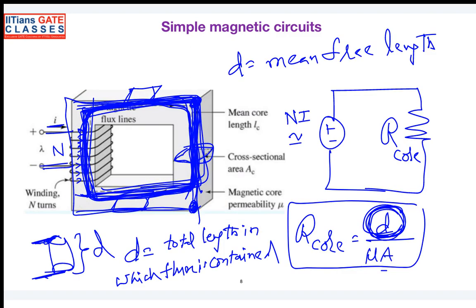What we came across till now is that when current is in this loop, there is a perpendicular flux. But in this particular case, you said it's in the entire core. No, the coil is not around the entire core, right? I was telling about this one. Whatever the dimensions of this core are, it is guiding the flux to go in that direction. Iron is basically a conductive material for flux. Whenever the flux is generated, since the boundary is restricted here, it is getting diverted to the other dimension.